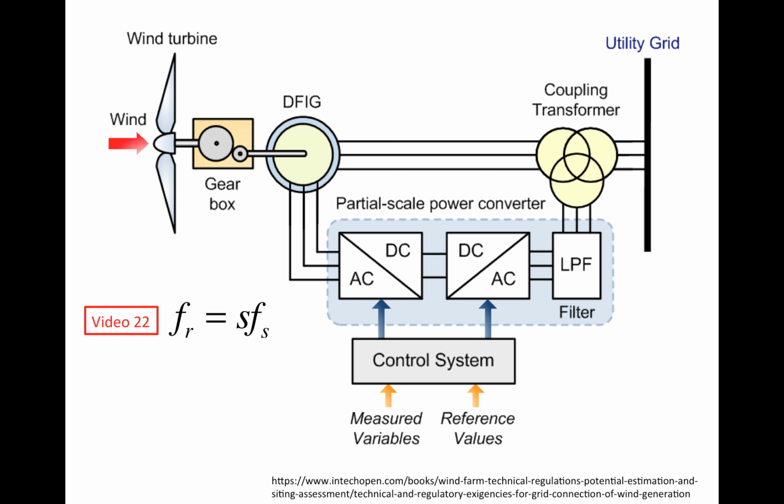It allows for a wide range of slip and also rotor speed, and it keeps the current in the generator constant. So the generator will not go over the rated power or rated current, so it's not going to burn. There's no danger of burning, right? So all the benefits of using an external resistor are kept.